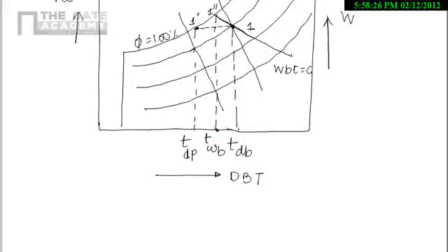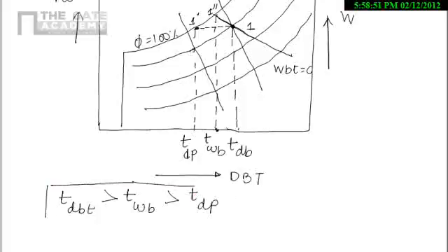So now how we can find out the dew point and wet bulb temperature on psychrometric chart? It is very clear, and from this diagram we can write the highest temperature will be dry bulb temperature, then wet bulb temperature, then the lowest temperature will be dew point temperature. So remember one thing, the dry bulb temperature is greater than wet bulb temperature is greater than dew point temperature.